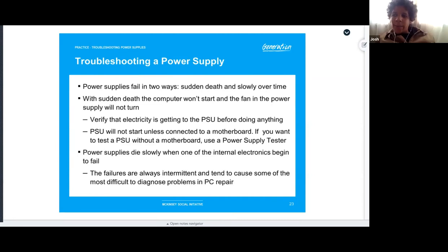Maybe you're losing power. Try the card in a different computer for some time. That's one thing you could do. You could swap it out, try it in another computer. What about using a multimeter, checking the power coming from the power supply to see if it's consistent? You're not seeing big drops. You know, it's coming through at a regular rate.